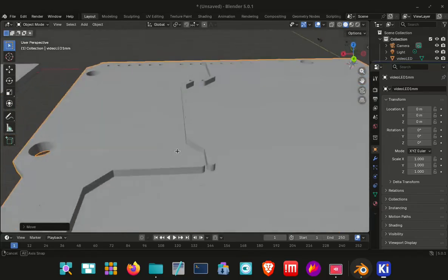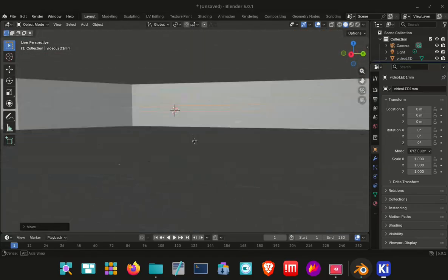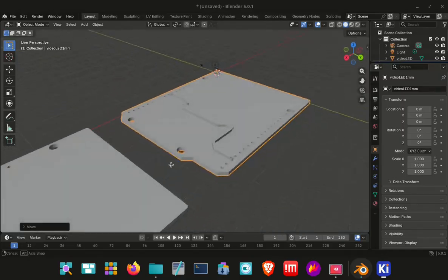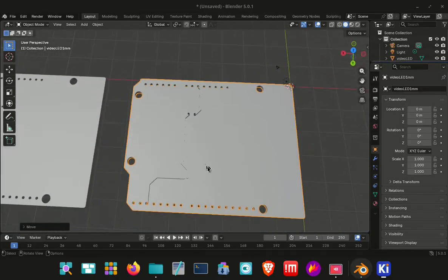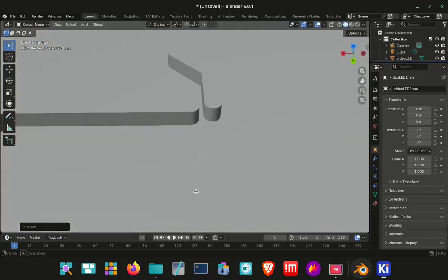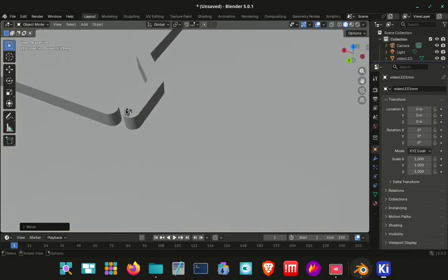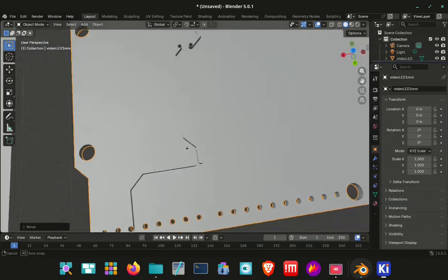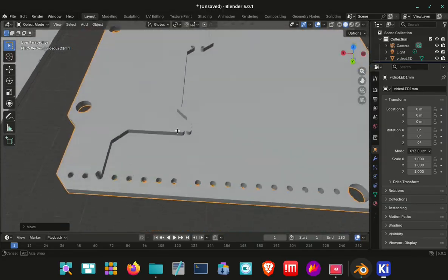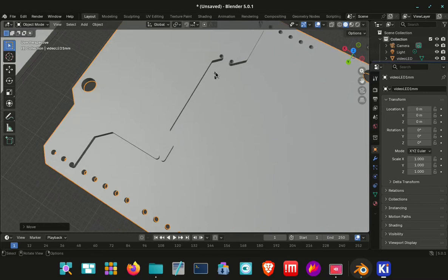And now you can see the tracks. They will actually print nicely like that, right? So you can change your track height. Exactly the same circuit, everything else. Tracks are different. Now, if you see here, right, we've got no holes. Now, if you were to want to print those holes, that's great. That's not great. I mean, you'd have to drill them.